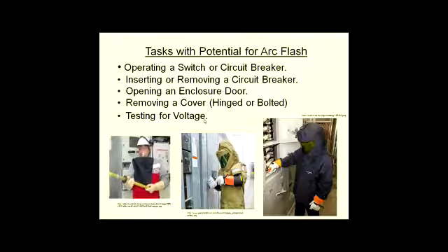Remember when we talked about the different categories of voltmeters or multimeters at the very beginning of this course? That's why different meters are designed to handle different types of power. If you have a consumer-rated multimeter and you try to measure something of higher power, that thing can actually blow up in your hands, all right? Because it's not designed to handle that, right?